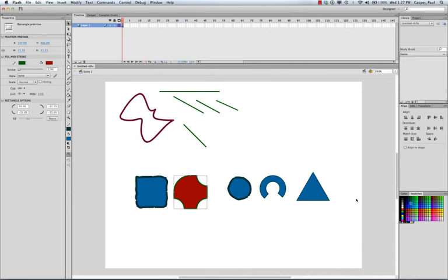And I'm going to go down in design mode here in Flash, and there's the color panel. Notice in the color panel, we've got our stroke color, our fill color, but in addition we've got a drop down that says the color type. Currently all we've really used was solid, but notice that there's some different gradients. We can do a linear gradient, radial gradient, and even a bitmap fill, so we can fill it with a bitmap picture. I'm going to start with a linear gradient. Linear means line, gradient that goes straight across.